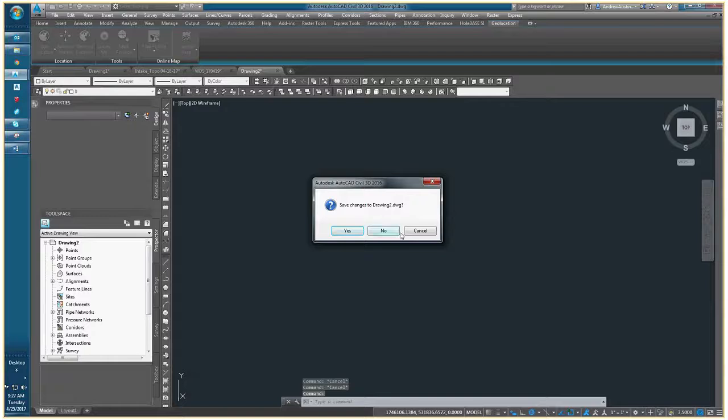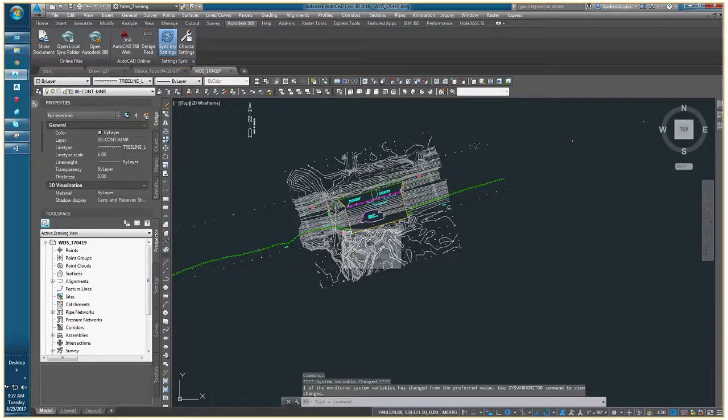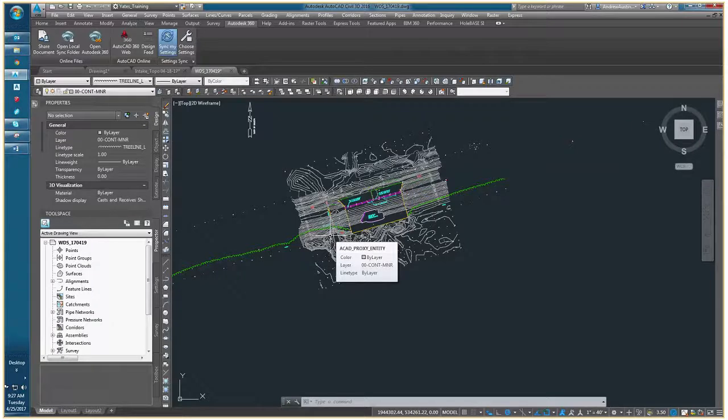Do you have to change the boundary line back to boundary so it won't print, or do you keep it? No, it stayed on the C10 boundary layer. If we wanted it to show up, we would have to make a change in the style of the surface as opposed to changing that particular contour. So that boundary that we added is part of the surface definition, but is still on a non-plot layer, which is not critical for our purposes because after this next step, we'll actually look at how that behaves in our drawing.